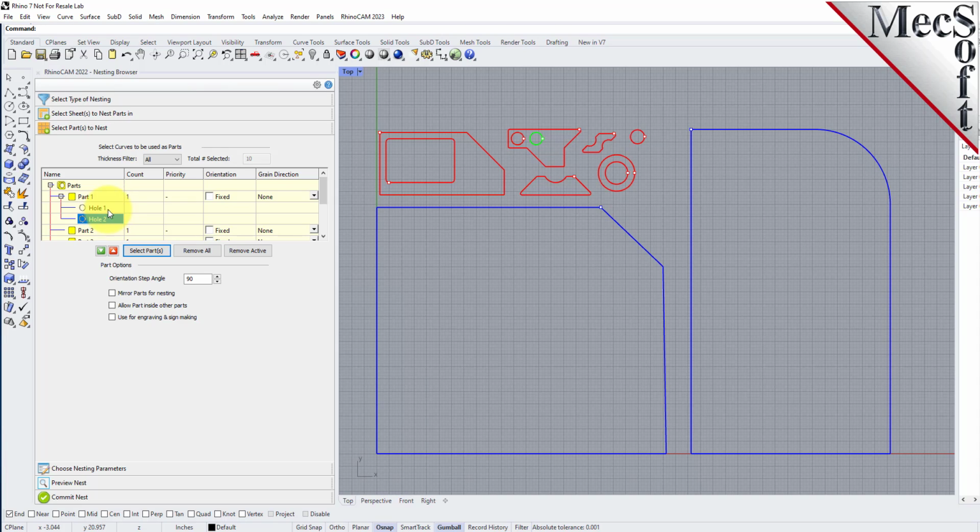Now, we'll enter the count for each of the parts that are needed in the nest. For this tutorial, you can use these amounts or adjust them to see different nesting results. Now we'll select the Count column from any part in the parts list and then type in 50 and press Enter. Since we want all parts to have the same count, we right-click on the count we just entered and select Make All the Same, and the counts for each part are updated.